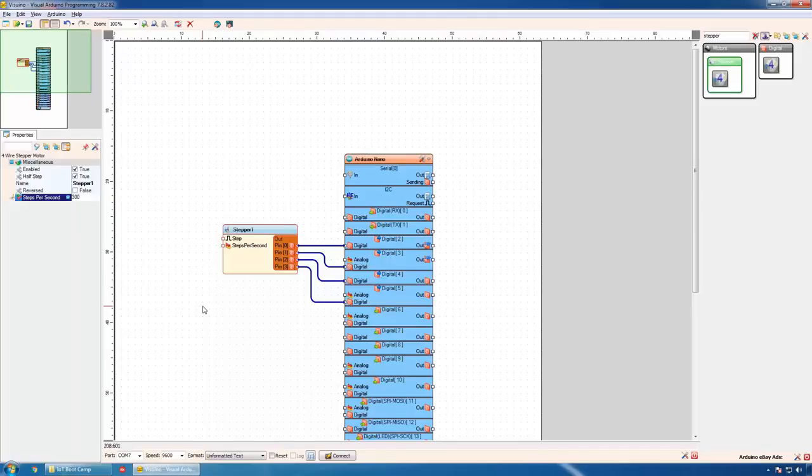The joystick will provide analog value between 0 and 1. We want to convert that to steps per second minus 300 to 300. The joystick, when released, does not always stay exactly in the middle, so it is nice to have a little insensitivity dead zone where the joystick value will be assumed to be 0.5 or 0 steps per second. Visuino has special component for this.